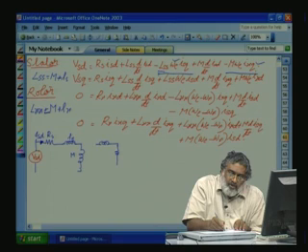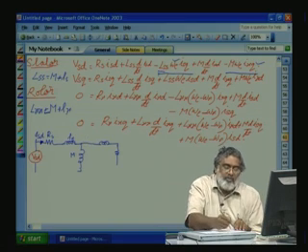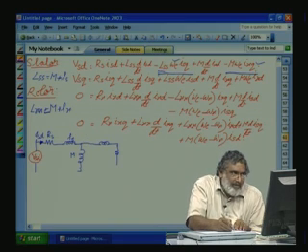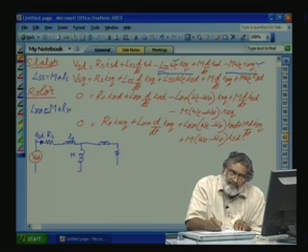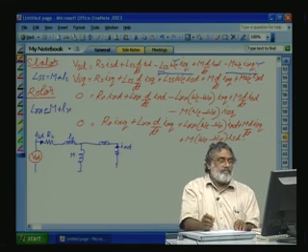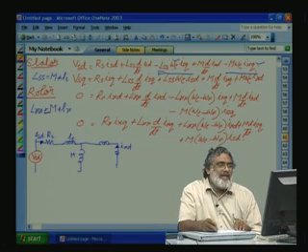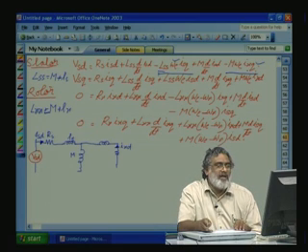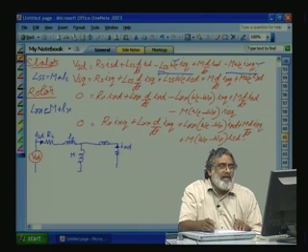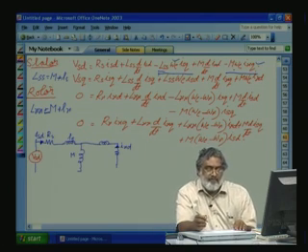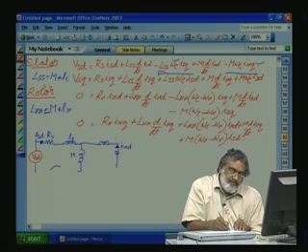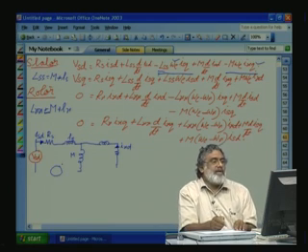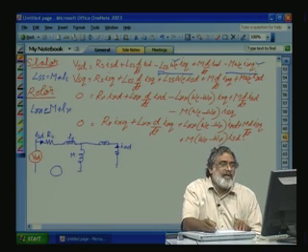Okay. So this also comes here. Through the mutual inductance term here, both ISD and IRD are flowing. So, IRD is here. Now, what is this LSS omega sigma ISQ plus IRQ? This is, we can say, the flux psi SQ. We will come to that later. So, there is a rotational voltage term appearing at the stator due to ISQ and IRQ.